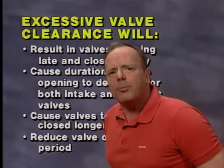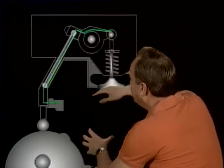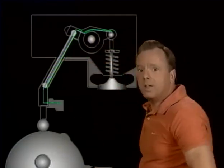Now let's take a look at some operating principles of a radial engine. One of the things they want you to know on a radial engine, and this will surprise you, is that when the engine is warm and you have operating valve clearance, the operating valve clearance is greater than when the engine is cold. Why? The reason is that the aluminum cylinder expands, pulling the top of the cylinder away from the cam ring, and the aluminum cylinder expands more than the steel push rod does. So when the engine is warm, the operating valve clearance is actually greater than when the engine is cold.